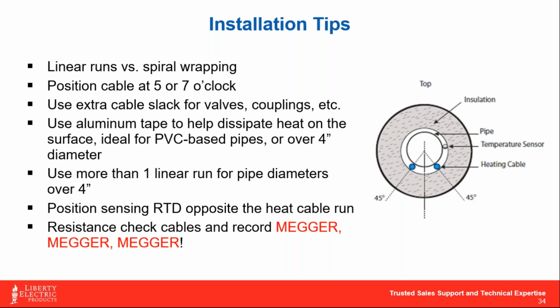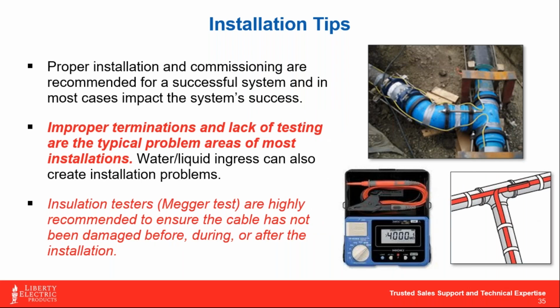So, the biggest thing when we're talking about installation is Megger testing. Basically every heat cable manufacturer is going to require that you use Megger testing for warranty purposes, but that's the easiest way to ensure the cable wasn't damaged during installation. For those of you who are not familiar with what a Megger tester is, it's similar to a multimeter, but we're not checking current and voltage values. All we're checking is the insulation value of the jacketing on that cable. When we send a test charge through it, if there's a cut in that jacketing or a leak to ground, this tool is going to show us that.